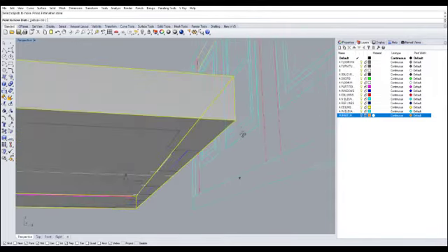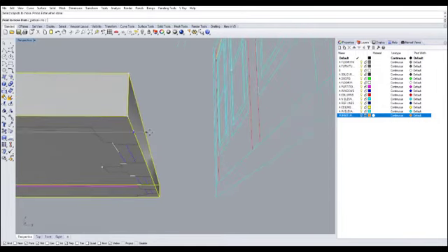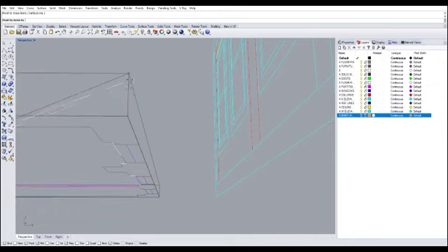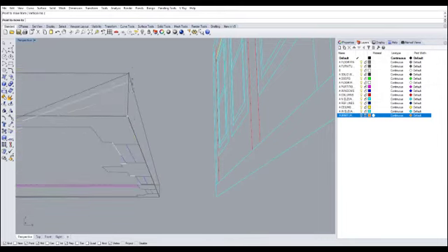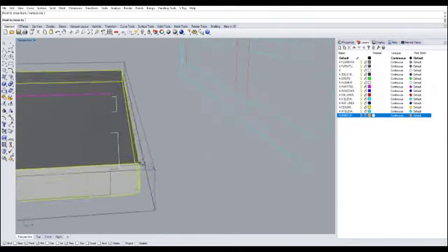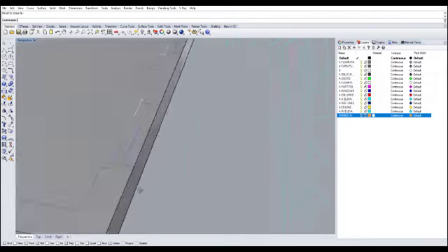We want to move this corner of the floor down below where the floor plan is, so we can see the floor plan. So let's do that. I'm going to click on that part where I want to move from. I'm going to move it down, again using that tracking. It locks up right there. Now that is directly below our floor plan. That's where we want it to be. I'm going to click it.